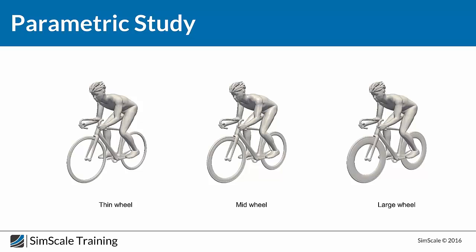Okay, perfect. Just like Milad already mentioned, we will do this case example where we have three different designs, and just to let you know, the cross-section of the tires is the same. The only difference is in this parameter, the chord length, because actually the profile of this wheel is almost like a wing because of the curvature and so on. So all we changed is the chord parameter. What I mean by chord is the distance from here to over here.